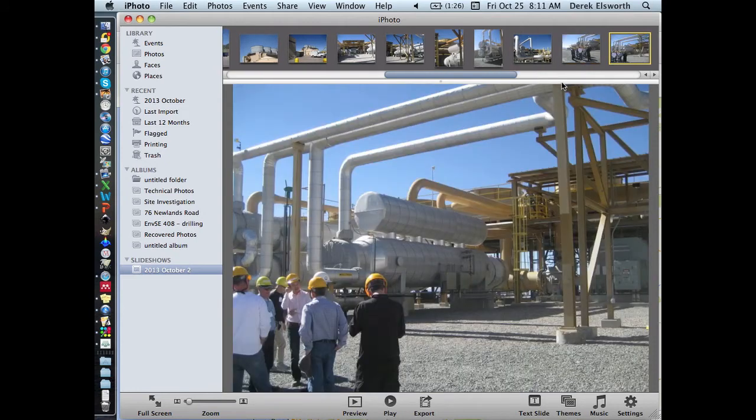So you have the hot brine going in here. It never contacts the isopropanol, but in this container here, it's a sinuous path, so there's lots of heat surface area between the pipes. The stuff outside it is this isopropanol. It transfers all the heat to that. That flashes and then runs through a turbine.